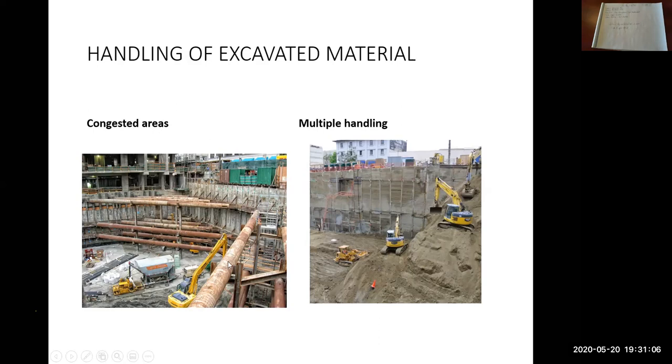Then these pipes here would be called struts. Those are braces in each corner of the excavation. They're pushing on the steel walers, again those steel beams that are helping support the shoring system. So all this steel that we see here is helping to hold up the walls of the excavation.